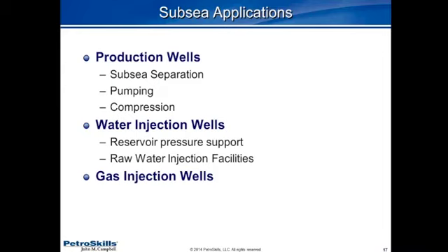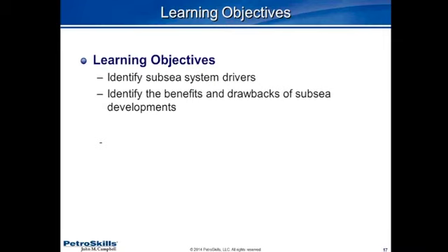Pumping is a way of adding energy to the production from the well, and therefore improving the recovery from the reservoir. And that's complemented by compression, which helps improve the production from gas reservoirs by reducing the pressure at the subsea system and moving the hydrocarbons to the production host.